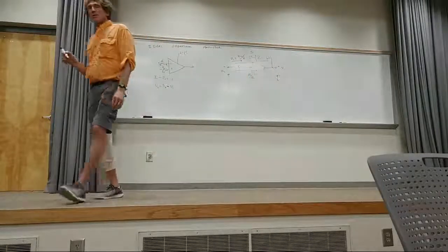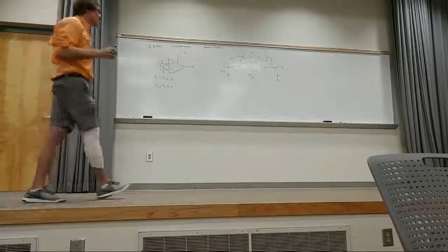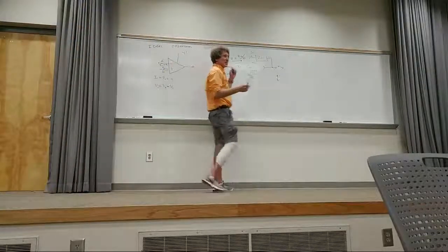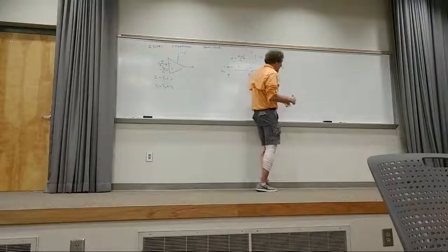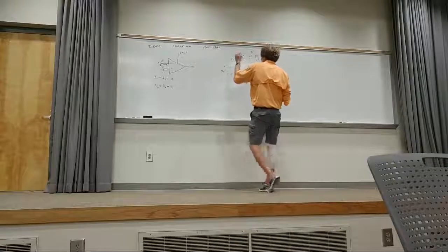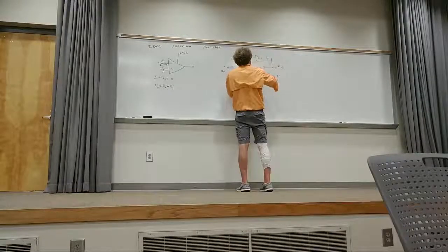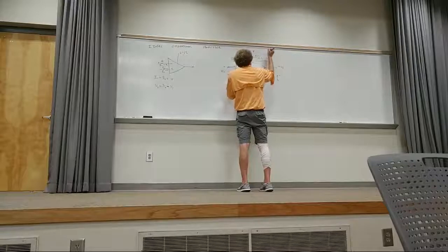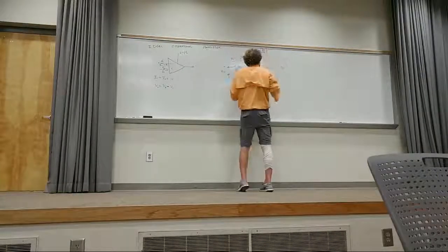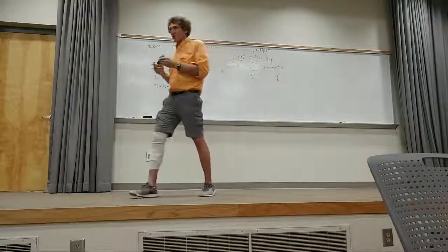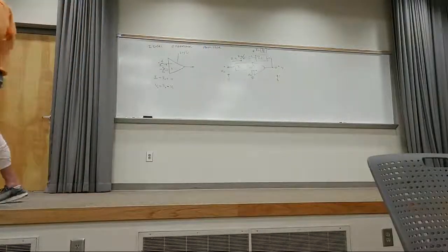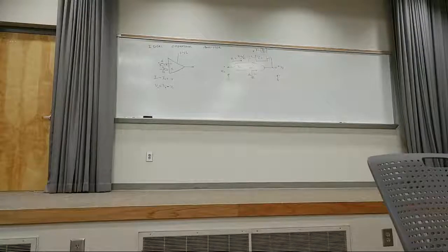Now, what's the voltage across Z2? I1 times Z2, right? Since I1 is Vn over Z1, I can say this voltage, and let me label it plainly, is simply I1 Z2, which is Vn times Z2 over Z1. You all see that would be the plus to minus voltage across there, right? Because the input current is Vn over Z1. Isn't it, class? Take a careful look. Convince yourself. It's not deep. This doesn't require a lot of deep thought. It's not looking 10 moves out of a chess game.